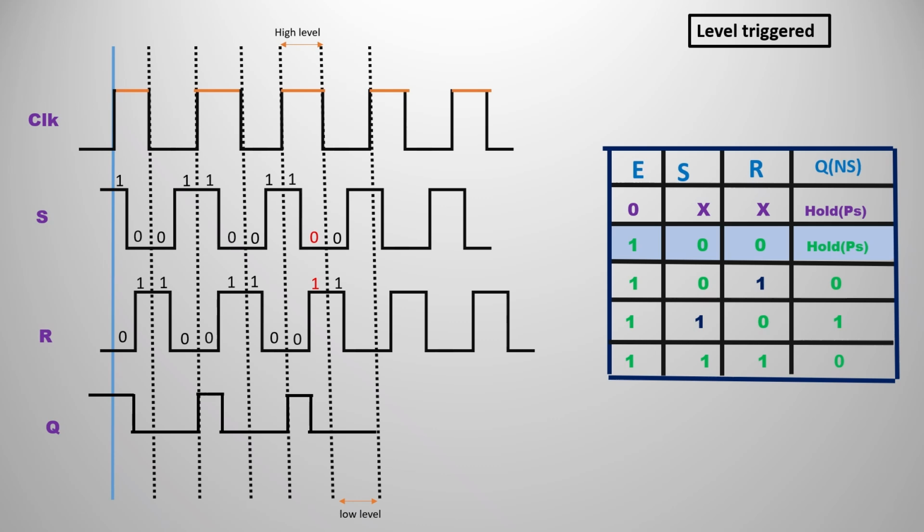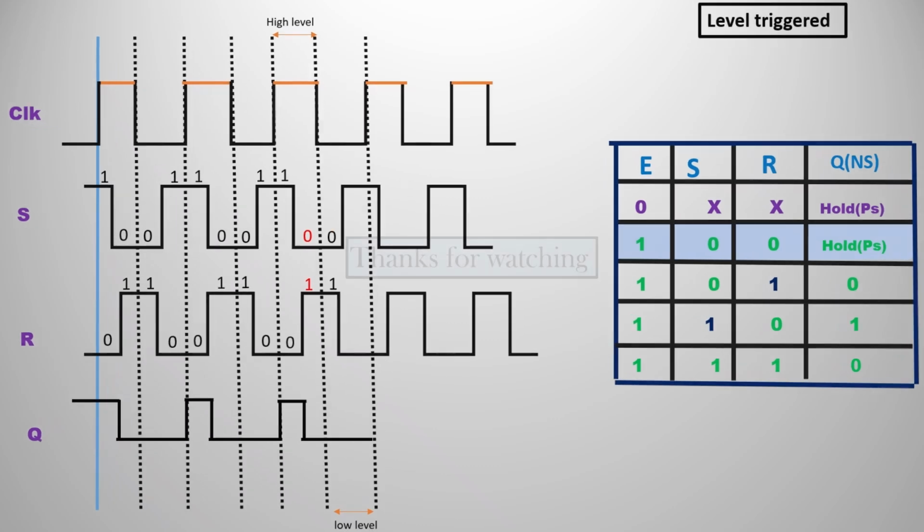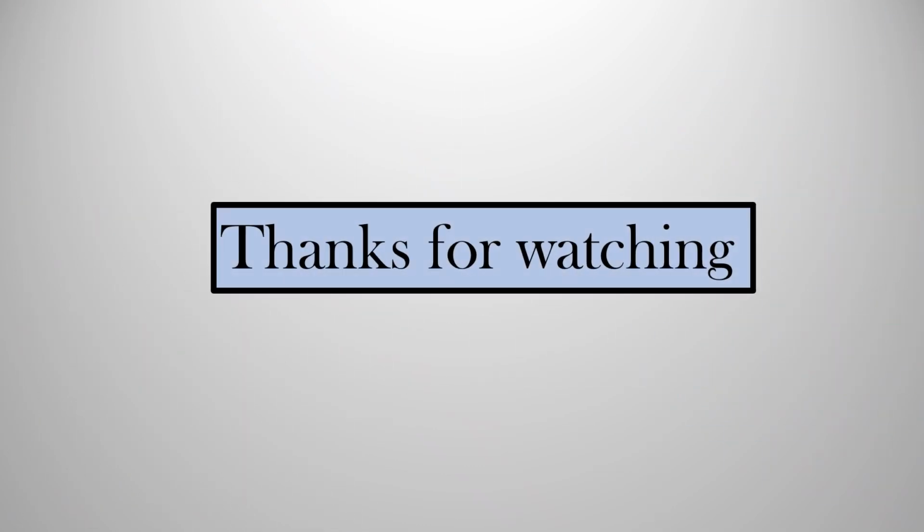If you consider this, it is the whole timing transition diagram of the output Q. You can just formulate the remaining clock pulses also. We can also simply formulate the Q bar, just the opposite of Q. That becomes our Q bar, which is also one of the outputs. I hope you understood this video, the implementation of latches with the help of the NOR gate.